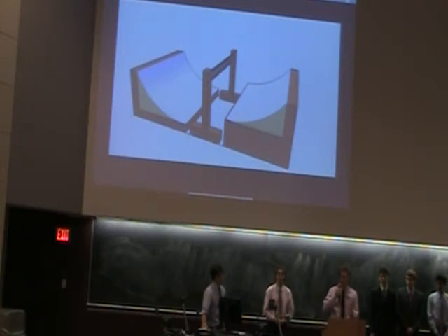And how this is constructed, it consists of about 4 parts. The first is the frame. That's the brown wood you see all around. That's holding up everything. Then on top of that, there are ribs, which are constructed to the shape of the curves that we specified in the program earlier. On top of that is a flexible piece of wood. And on top of that is a shiny piece of mylar, which is basically a very reflective piece of plastic. Light comes down, reflects off of it, and onto our panel. The mylar isn't perfectly reflective, and our curves aren't perfect in construction, but we believe that they're good enough that we should be able to get some strong concentration out of it.